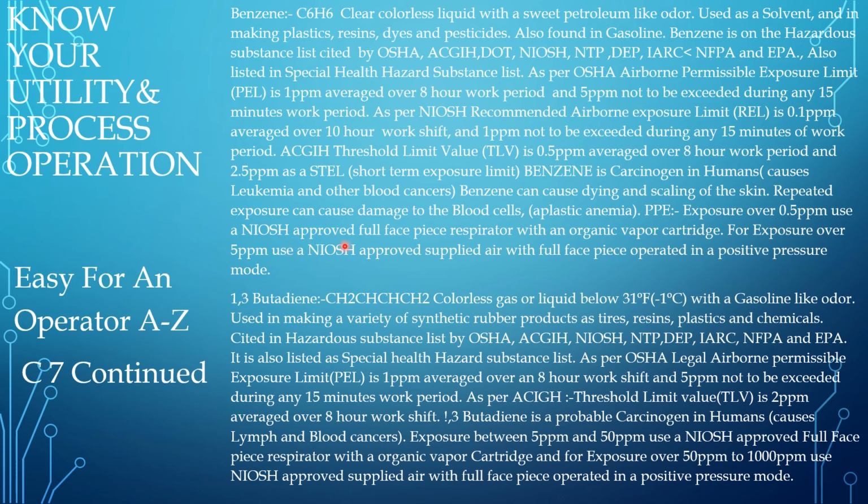The PPE required for exposure over 0.5 ppm is a NIOSH approved full face respirator with an organic vapor cartridge. For exposure over 5 ppm, use a NIOSH approved supplied air full face respirator operated in a pressure demand mode.